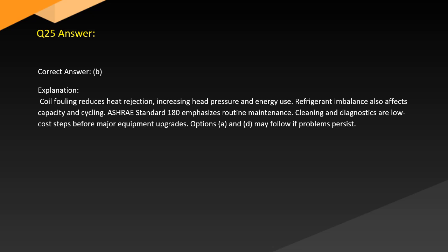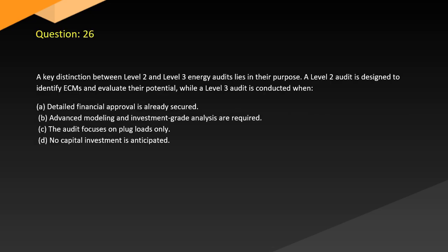Answer. Correct answer: B. Explanation. Coil fouling reduces heat rejection, increasing head pressure and energy use. Refrigerant imbalance also affects capacity and cycling. ASHRAE Standard 180 emphasizes routine maintenance. Cleaning and diagnostics are low-cost steps before major equipment upgrades. Options A and D may follow if problems persist.